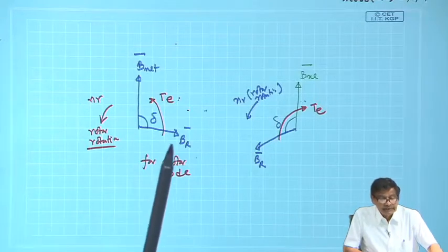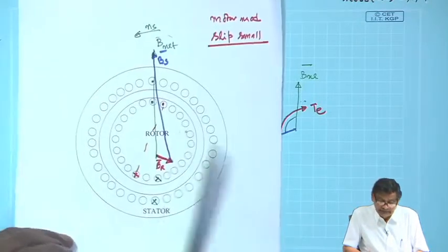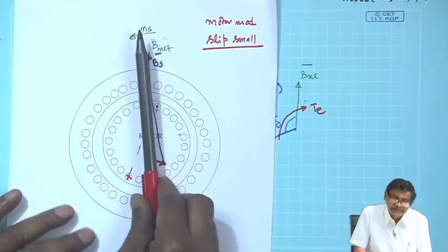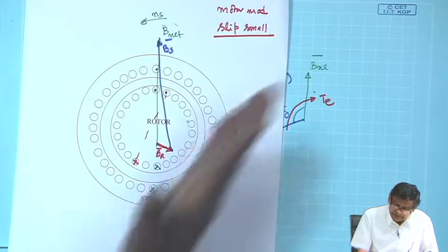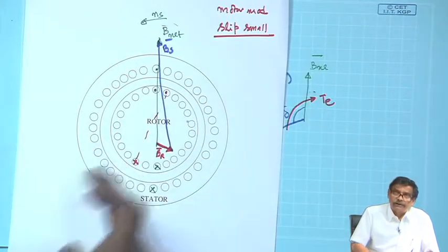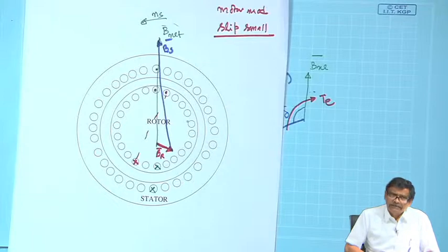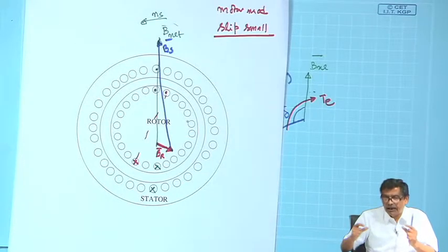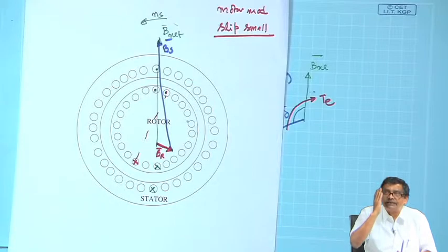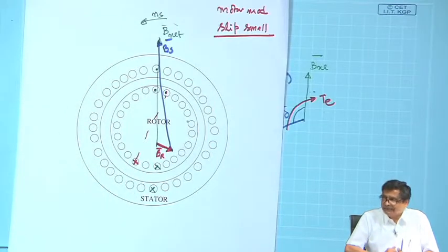And not only that, coupled with this idea that at any instant when I am drawing BS naught here, the resultant field of stator or rotor is difficult, since they are carrying time varying current, no doubt, but at least I am sure when, for example, A phase instantaneous current is maximum, perpendicular to the A phase coil magnetic axis, your resultant field is lying.